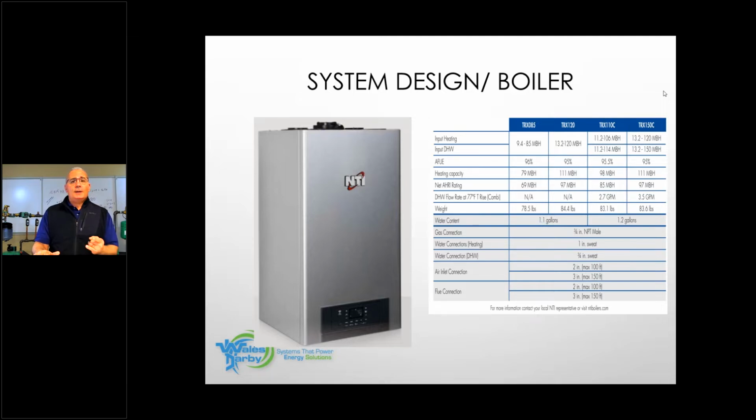It's going to be a two-pipe system. We're going to bring in outdoor air for combustion, and then we're going to vent either through a chimney chase or through the sidewall. Another very unique thing about this boiler is it comes with built-in Wi-Fi. As an NTI installer, if you install this boiler, register it for Wi-Fi, you can run it two ways. You can run it off of outdoor reset, which comes with a module that you would hang outside the building, or you can run it based off of internet weather, so the boiler will follow a weather pattern for its local area.